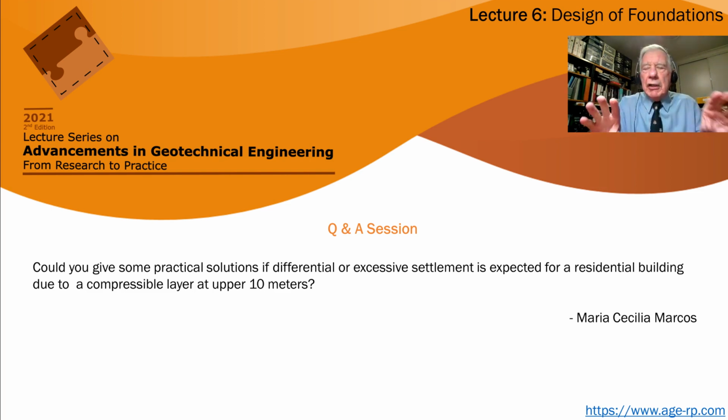About using shallow foundations, as I mentioned before, if you have individual footings and they're not tied together, the risks of having horizontal strains are much greater. And so the potential for damage of your building is much greater.